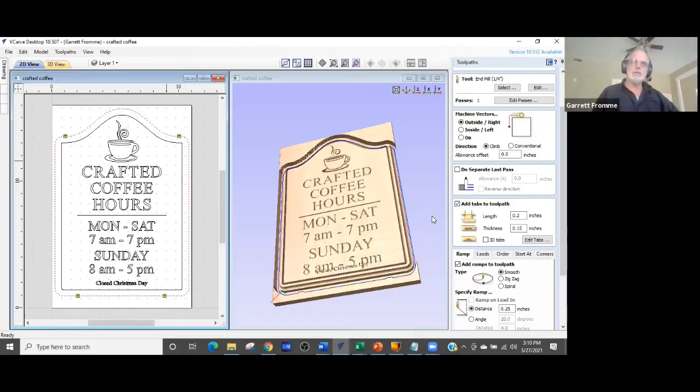The thing I don't like about straight bits is it's not using the shearing action of the cutting blade as a spiral bit would. Instead, you're coming in with the entire blade in one shot, and it's trying to work that entire surface. Now it'll work. It works on your standard routers. It will work in a router machine. It's just that your forces are a little bit different, because you've got a moving component that's got lots of moving parts on it that's trying to move around. So you may notice a little rougher finish and it may be a little more challenging for the machine. It actually is very distinct.